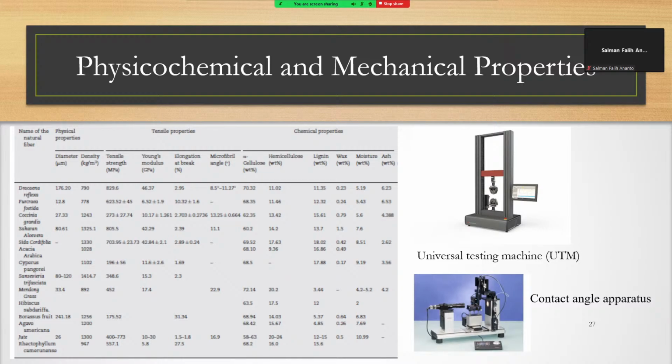The fiber should be tested under tensile loading following the ASTM C1557 or ASTM D3822-07 standard using a universal testing machine in order to obtain high precision. It is recommended to perform the test with a servo-electric tensile machine with a 5 kilonewton load cell or less.